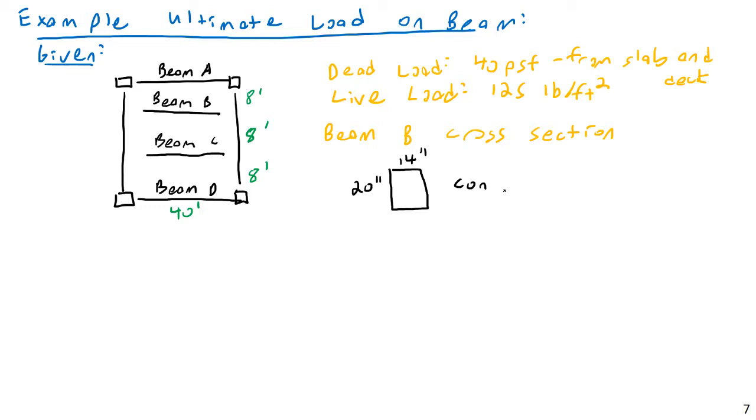But concrete, because it's made from so many different things, not only different types of cement, but different types of aggregate, different levels of air entrainment, different water-cement ratios, etc., concrete's density or its specific weight is going to vary quite a bit depending on the way the mix is designed. So my default value, if I'm not given any other information, I'll personally assume that it has a density, including reinforcement, of 150 pounds per cubic foot, but often we do have the information handy when we're designing things.